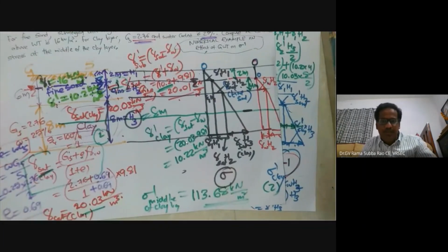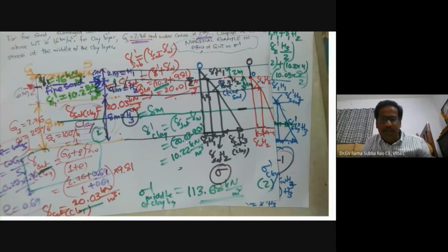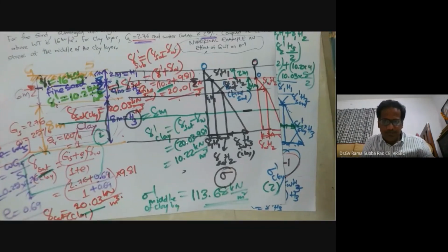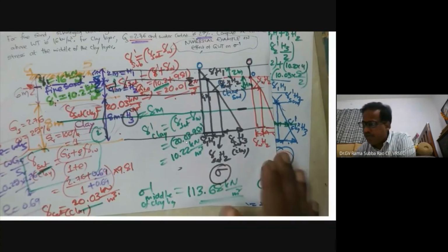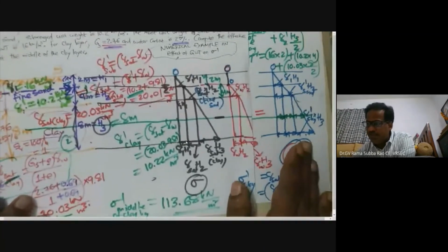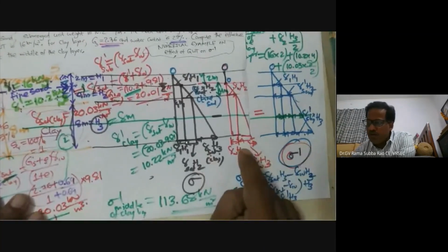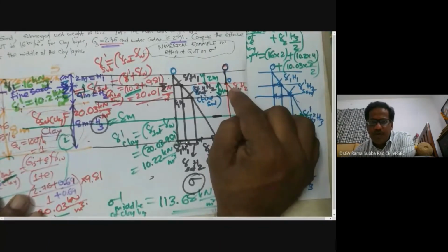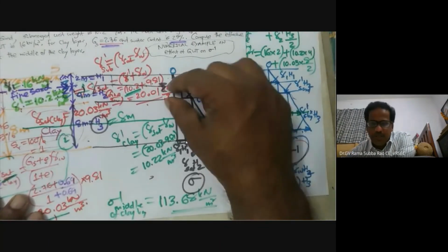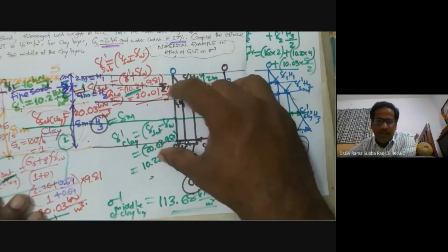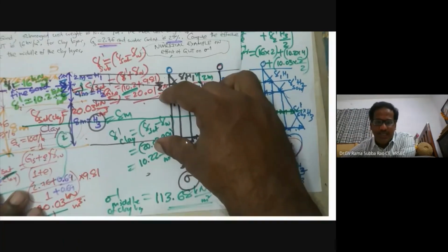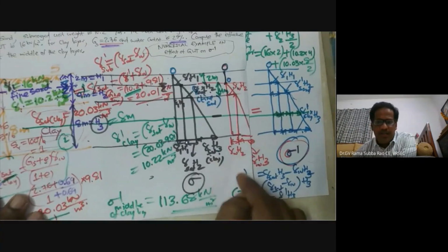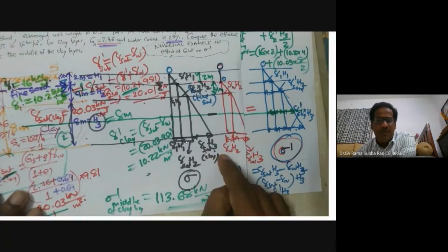table is present. So first we are concentrating on total stress, then pore water pressure, and finally we are determining effective stress. One can see here sigma, u: no water table, u is 0. If the water table is there, you take gamma of water into height of water. Here you see height of water is h2. When it comes to the second layer, it is h2 plus h3. That's why I'm writing gamma w. If you take gamma w common, it gives gamma w into h2 plus h3.